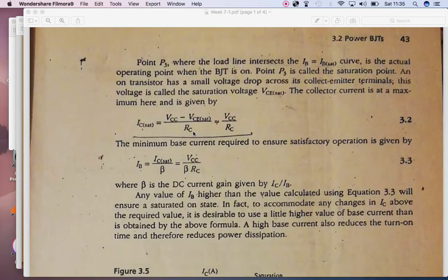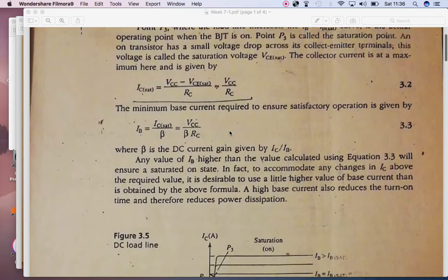So first to remember is this formula, which is the output current in the power BJT, which is IC. For that we have to take into consideration VCC, the biasing voltage, minus the output voltage, divided by the collector resistance, and we can also calculate its maximum value by taking this expression which involves VCC and RC.